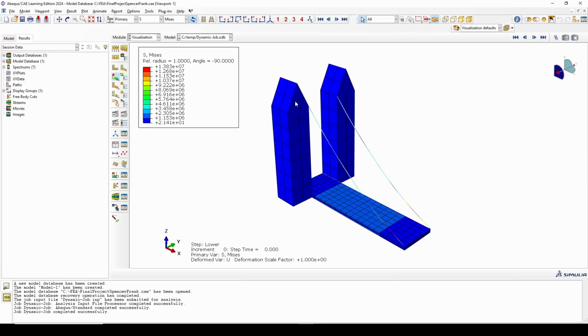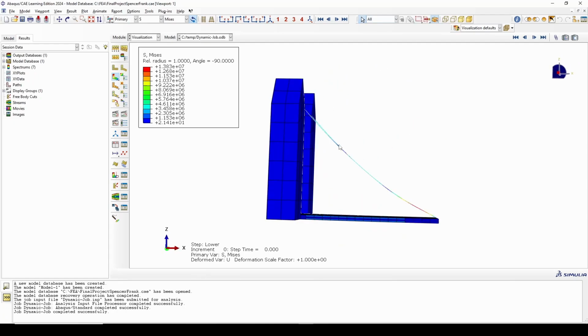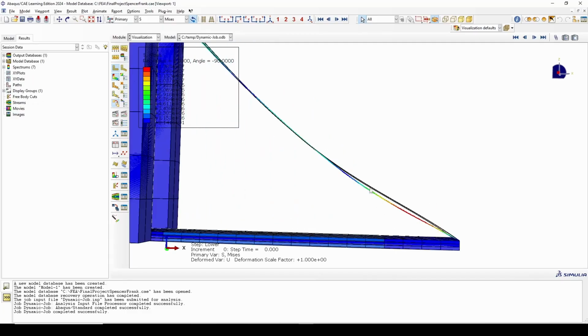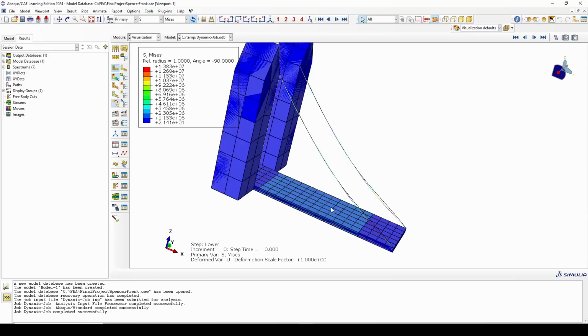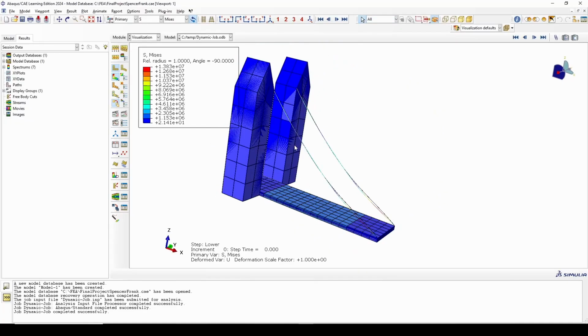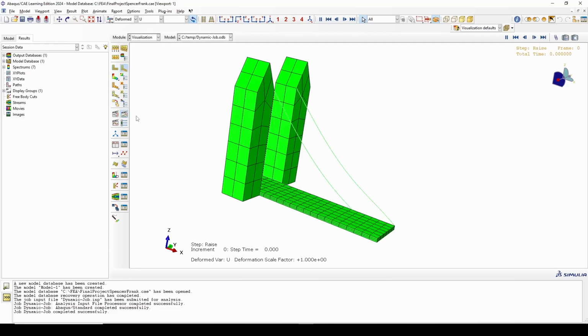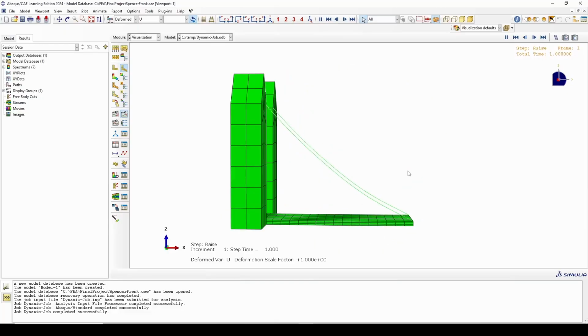These are the results of the static simulation, where there's this fixed end bridge condition. You can see that there's a lot of stress in the cables, and it does deform a little bit due to the gravity load. It has more of an arc here, and there are some stresses experienced in the center of the bridge. If I were to play the animation, this isn't intended to be a dynamic loading scenario, but you can see that the gravity is acting upon the cables.